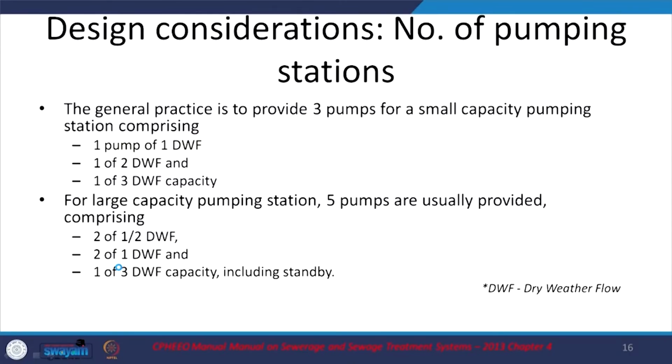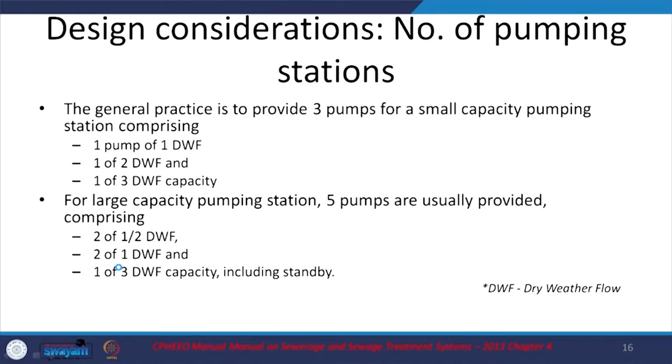We take it into account by seeing to it that even with the largest pumping station disabled, offline, or under repair, the system can still handle the peak flow, right. So, that is something to keep in mind. There is always going to be a fallback option. So, we are going to look at two aspects.